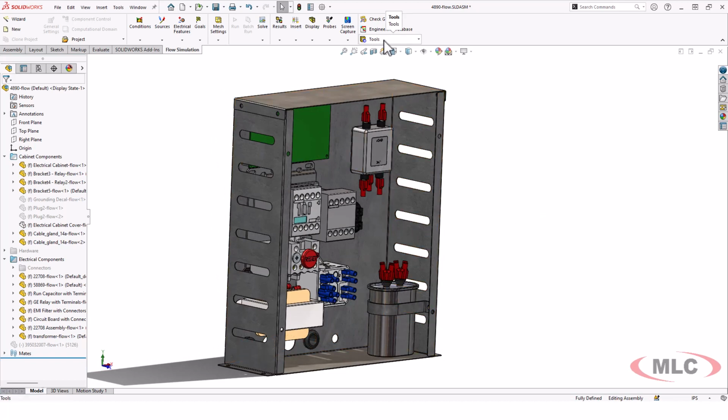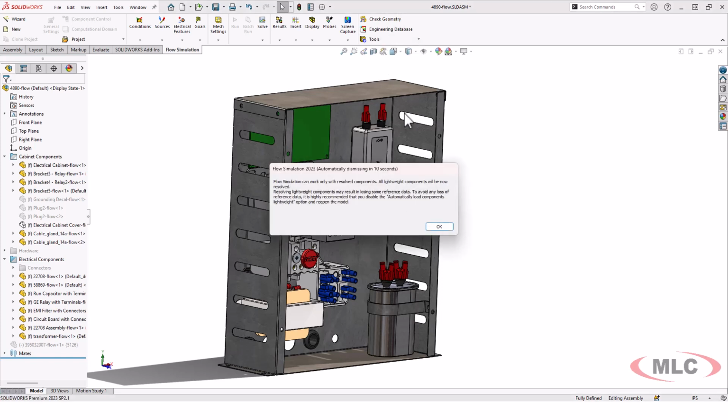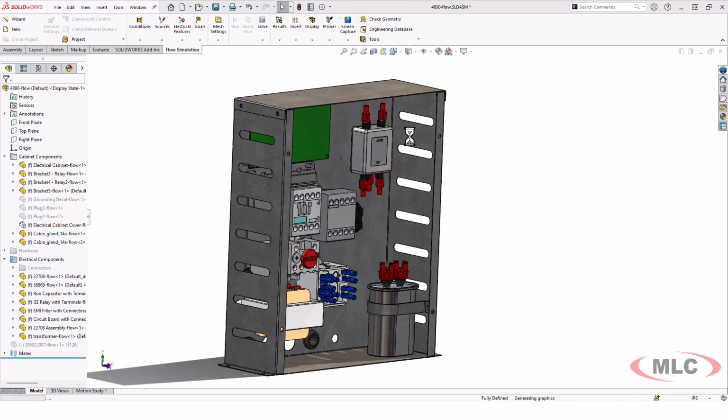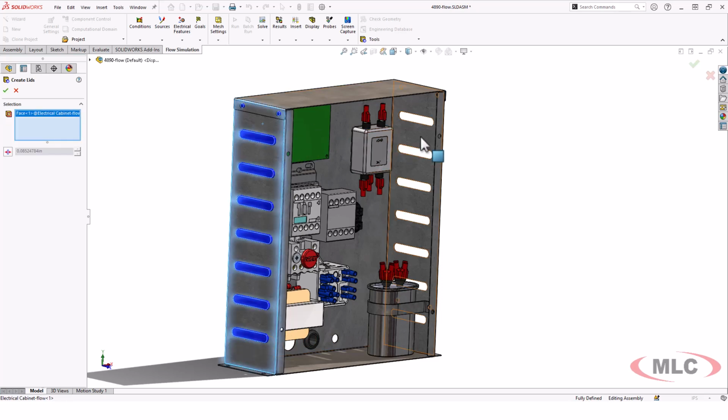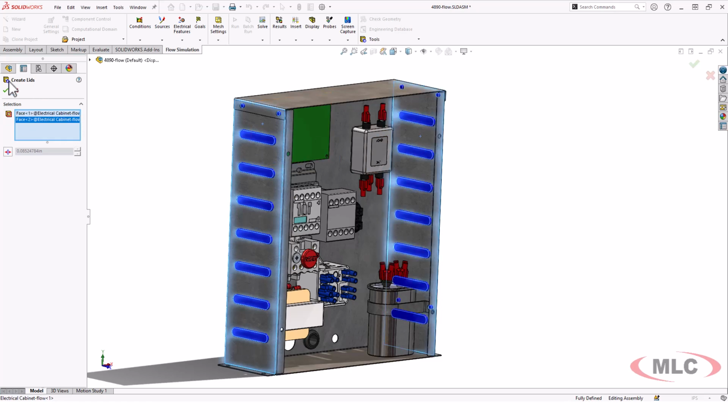And lid tools, for some assemblies, for some models, that's all you need is a few lids. And the lid tool is really easy to do. You just click a flat face and it creates a solid body. I'm going to grab the outside face here, and then I'm going to grab the inside face over here. And I want to do that just to show you what's going on and make you aware that you really do have to pay close attention to some of the details.